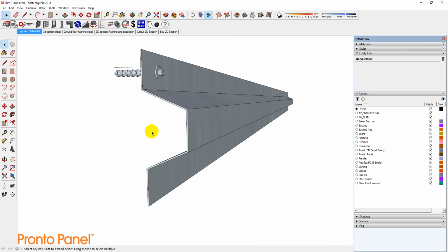After you freeform an object, make sure that you BIM it straight away, and then what you can do is just make duplicates or copies, and therefore every copy you make will be added to your bill of quantity in your Takeoff. So let's take a look how you do it.